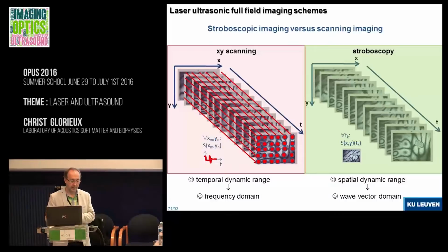But in scanning techniques, if you have one oscilloscope trace, you have like 30,000 points in 1 second. So you gain in spatial dynamic range, but you lose a lot in temporal dynamic range unless you measure for very long times. But the purpose is to have a large image, not time resolved, but at least one image quickly. Yeah, you have that.